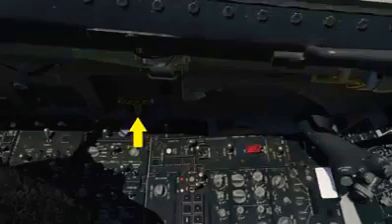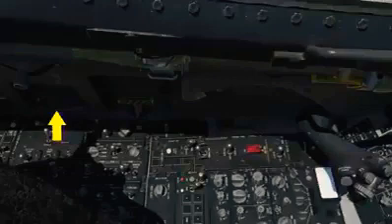If the guard is not down, you'll get the canopy eyebrow light. In case of emergency, you can pull the canopy jettison handle. This will be used if the primary ejection handle is pulled, but the canopy fails to separate from the aircraft, preventing ejection. The defog lever can be moved forward and back to provide defogging of the canopy.